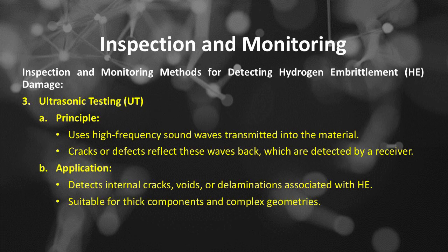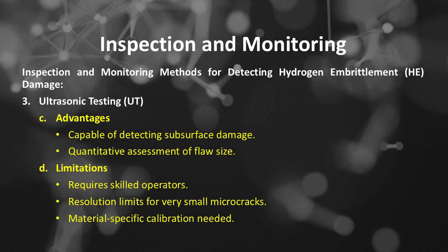Ultrasonic testing advantages include being capable of detecting subsurface damage and quantitative assessment of flaw size. Ultrasonic testing limitations include requiring skilled operators, resolution limits for very small microcracks, and material-specific calibration needed.